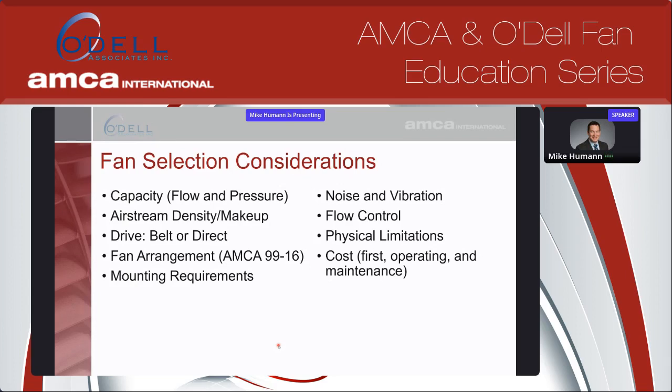These two are really critical to any basic fan selection. The rest of these items really just enhance or can better help us select the best fan for that application. Some of the other considerations: if you're looking for a belt or a direct drive fan, if you have a specific fan arrangement in mind, and any specific mounting requirements depending on the site or the application.